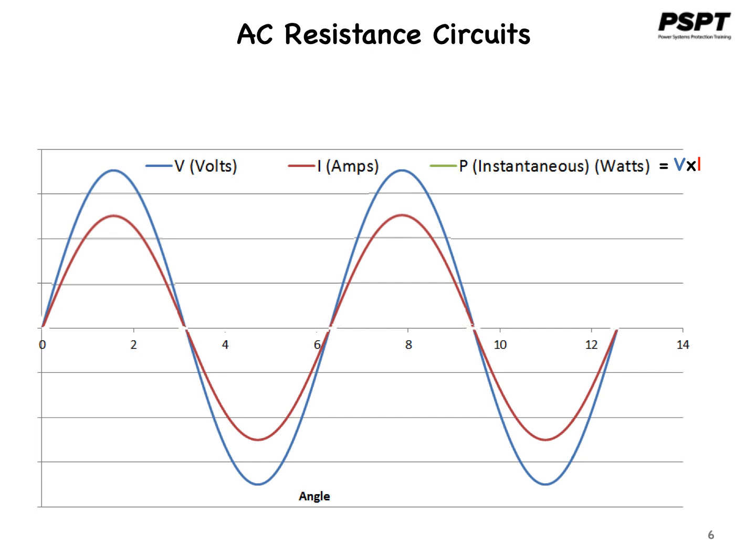We can also calculate the power dissipated by the resistor by multiplying the instantaneous voltage times the instantaneous current, or P equals V times I, and plot those values on the same graph. Note that the power is never negative in value. When the current is positive above the line, the voltage is also positive, resulting in a positive value.